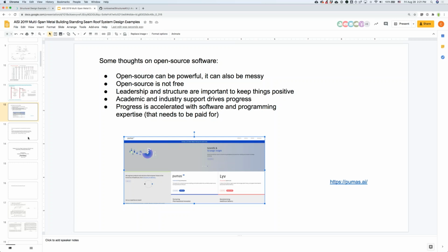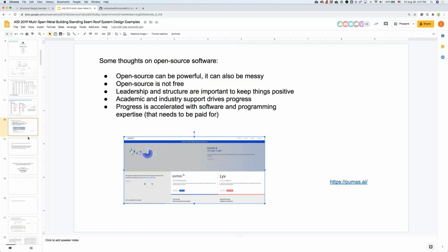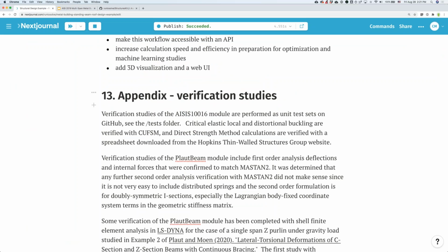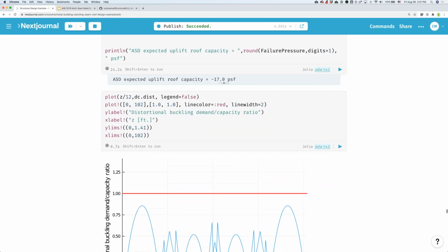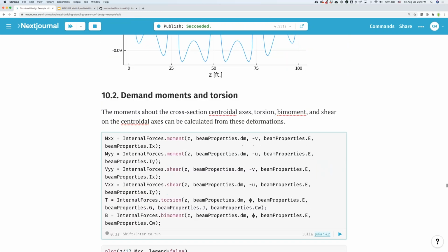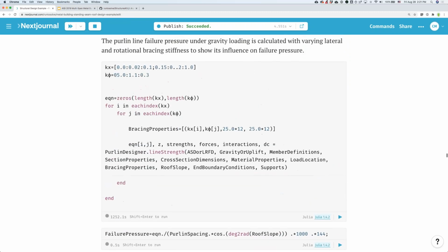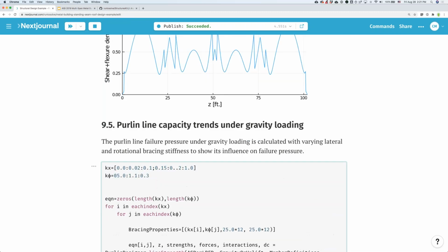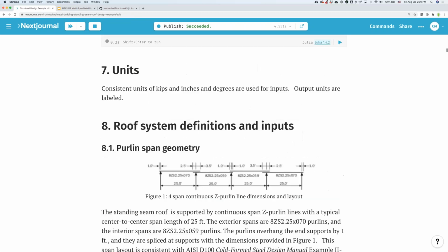First question: is this being modeled as nested sections acting as if they are fully adhered? I've seen evidence of ply separation in tests, especially when you have slotted lap connections. Seems like that would impact the behavior over the support. Yeah, support topic is tricky. Pretty much what we did is what most people do, or what I understood from the existing examples. Where they overlap, you just add the cross-section properties together. I don't know if that is correct or not, but that's what has been done here.